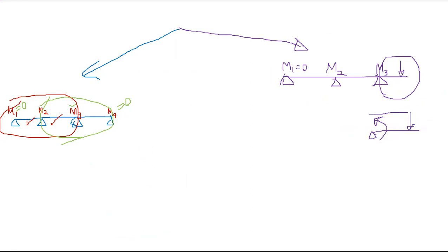So this is going to bend this beam in this way. The resistive moment M3 can be found by, if it is P and this is L, P into L. M3 is P times L. That you can easily determine.